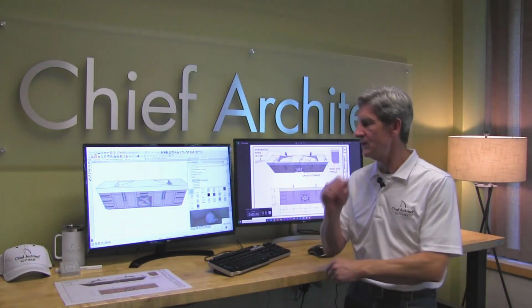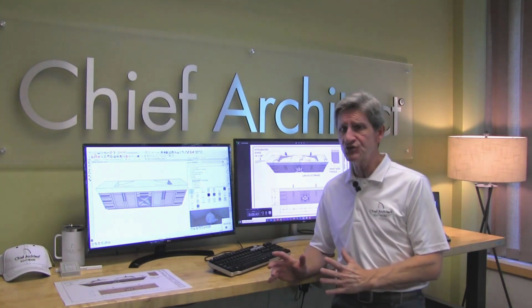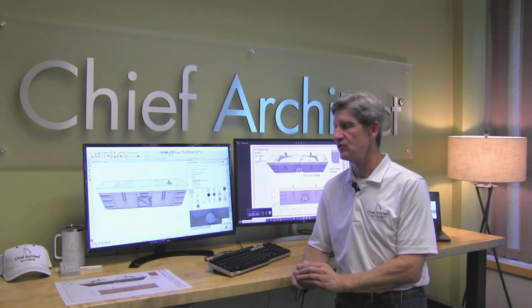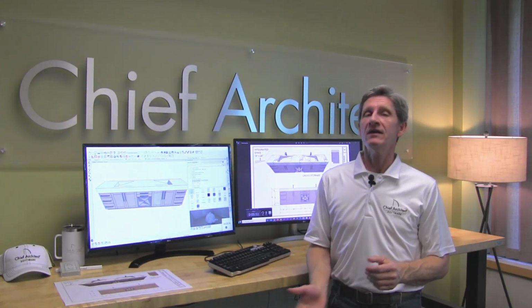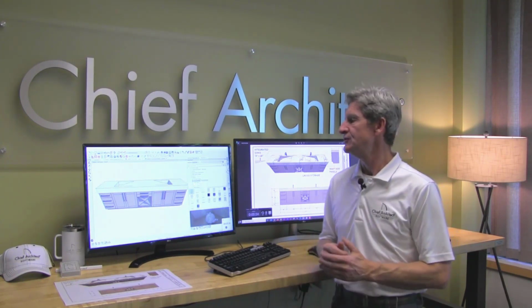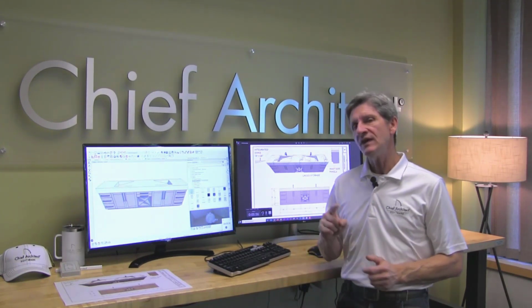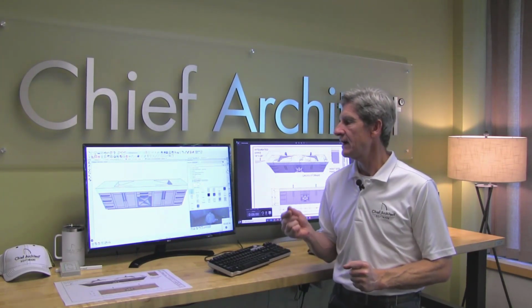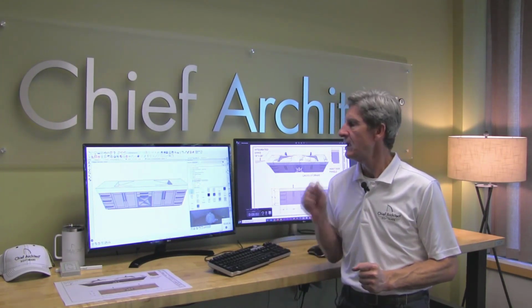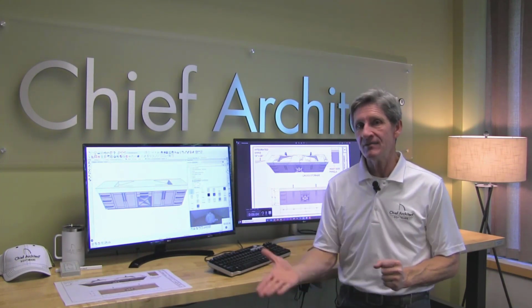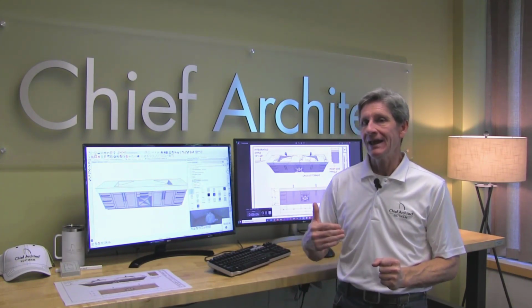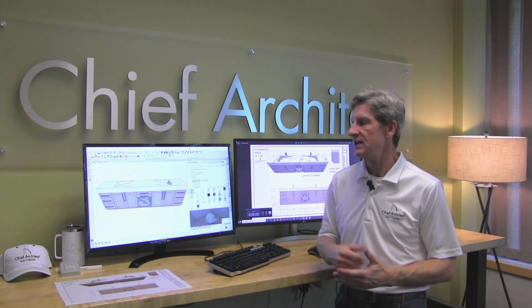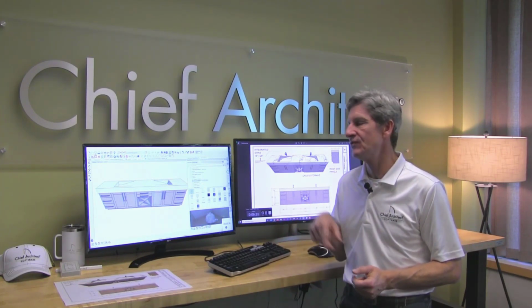Let's talk about what we just did here. When I drew those CAD objects and converted them into a 3D solid, it required a custom countertop to subtract those. And once I did that subtraction, it actually changed the property from that countertop to a 3D solid. And the cabinet said that they had an automatic countertop, and it came back and it was competing with that 3D solid. So I had to go back in and remove those.